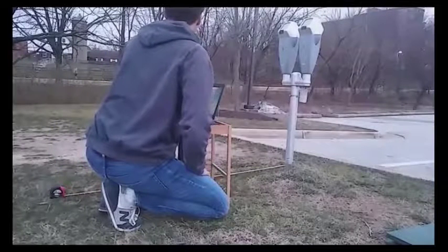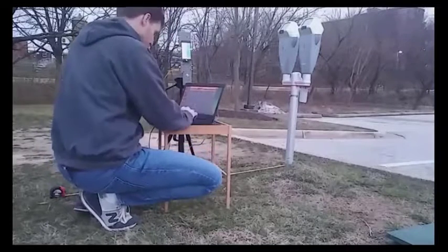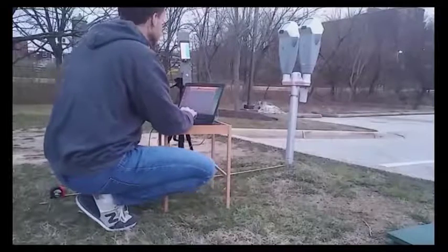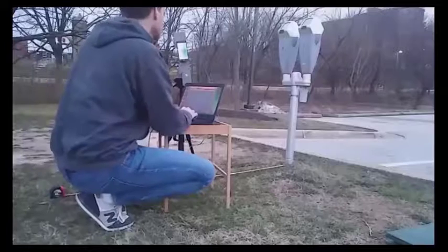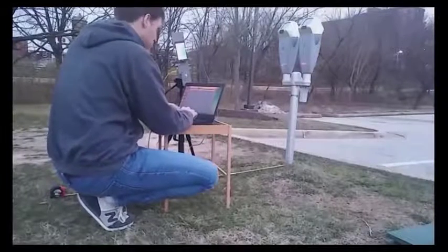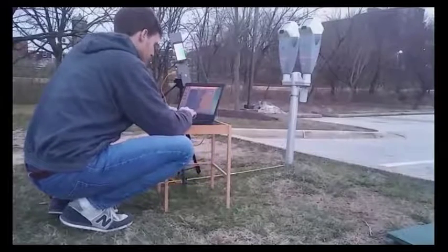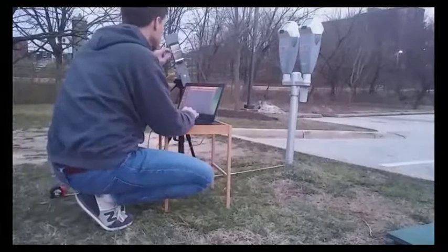Here we are again on site and actively mapping the parking meter. As you'll see, I start off with the LiDAR at a level 0 degrees and run the Python code on the Raspberry Pi to take the first image. I then tilt the LiDAR mount, run the code again, input the new degree value for the tilt of the setup, and save the next image. I build up a series of these images that are saved into the main folder on the Pi, which can then be easily transferred to my laptop through email.